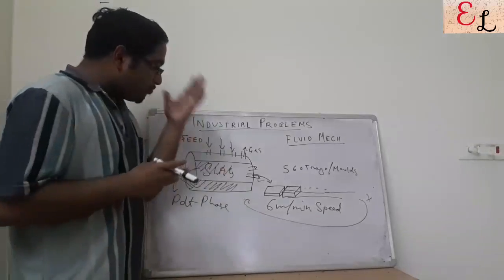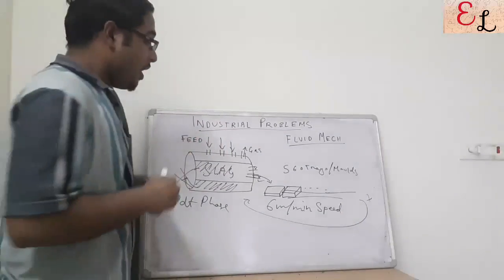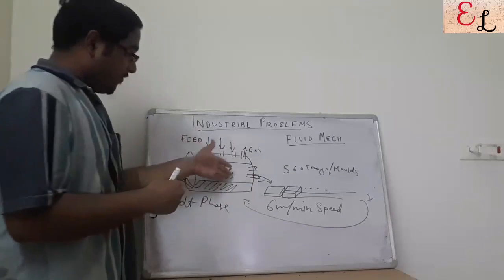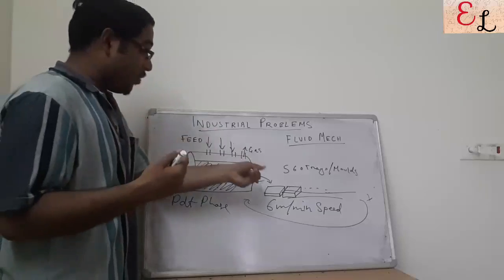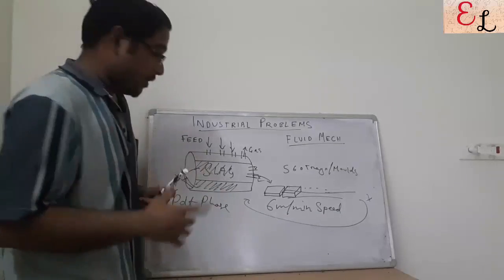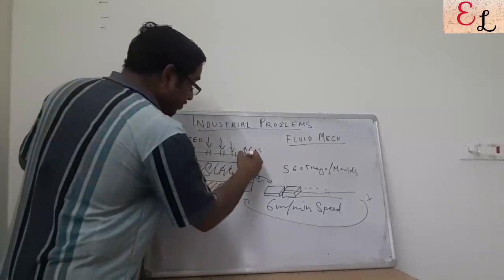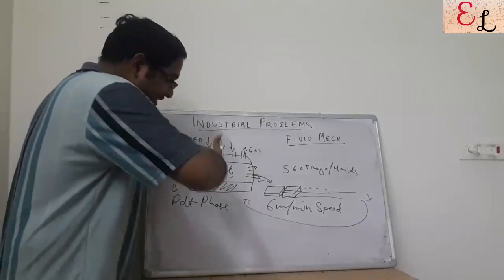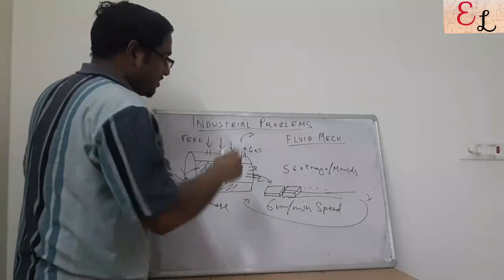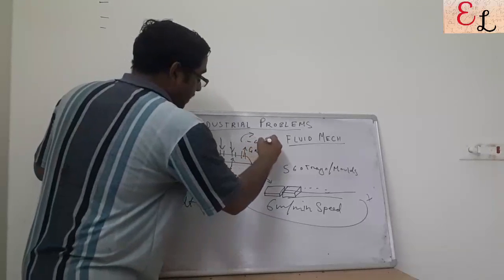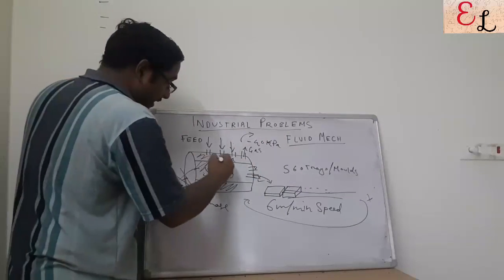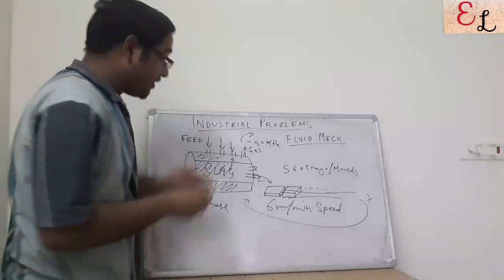So what we did was a simple calculation. What was the calculation? What is the amount of pressure that this fluid bed above this tapping point is creating on the tapping point? This is the calculation that we did. Now this calculation was not simple because there was a constant suction of gas. The gas that was formed due to the reaction was being constantly pulled out by a suction force. Now the suction is giving a minus 40 kPa pressure.